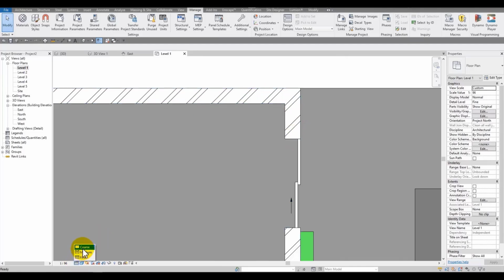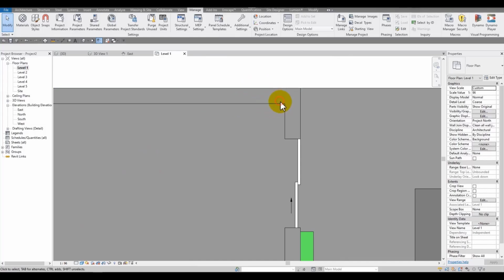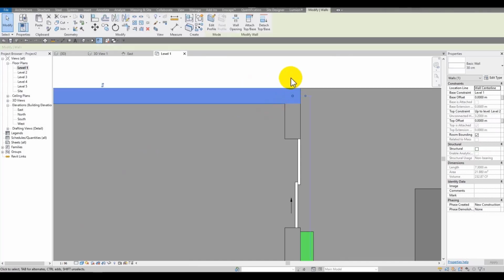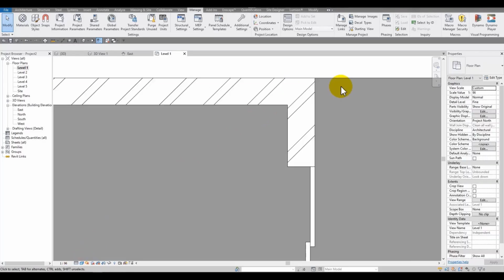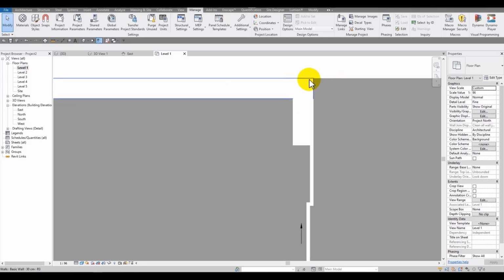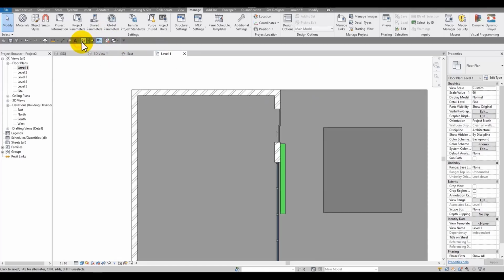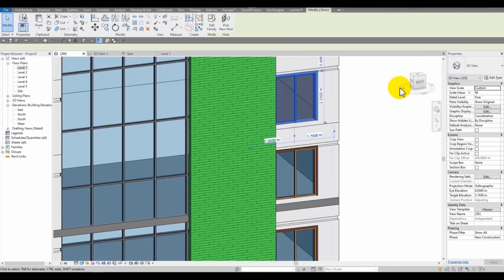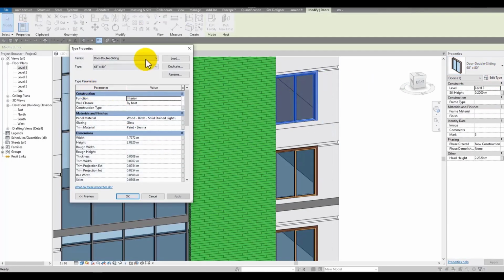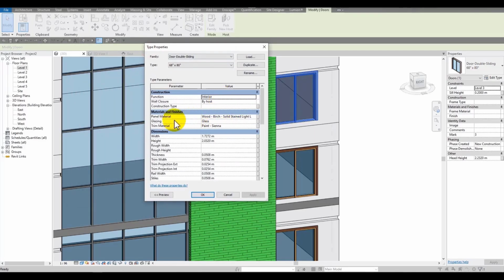And when I change this to coarse detail of view, it's not possible to see the color and hatch of the wall anymore for the part which is cut. But level of detail, put it in 5 to be able to see everything like hatch and the color of this section. Guys, these are the least possible amount of the information which we can have about the materials.